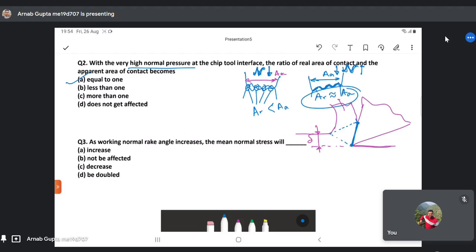Okay, so you can divide this area into two zones. So initially the contact pressure will be very high. Here the value of normal force is very high, which slowly decreases in the upper portion. So this one will be the sticking zone, where we can say the value of mu is not constant.